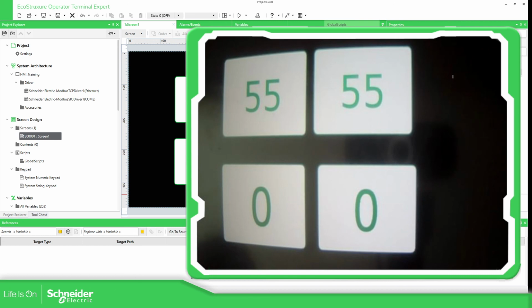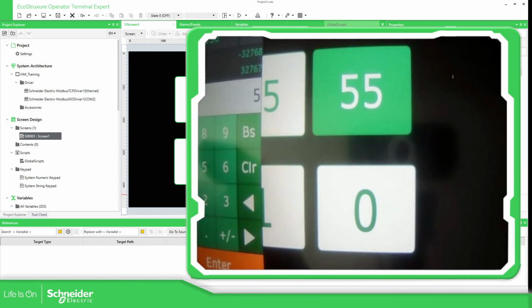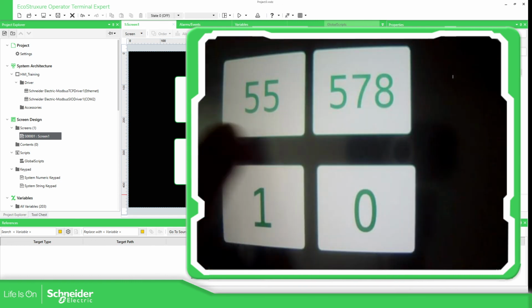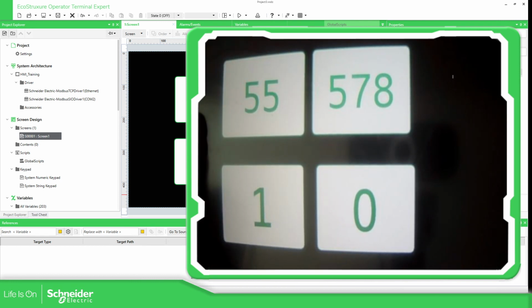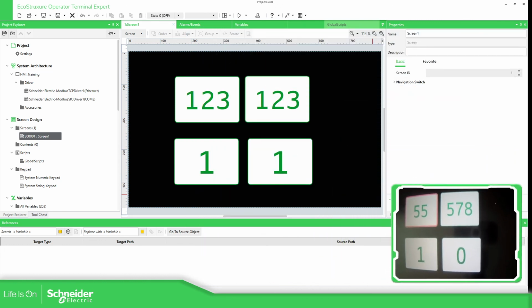Now what I'm going to do is remove the Ethernet port that I have. So it's going to be this side. Okay, so I have removed it. You can see the one that is in fault, and this value is not going to be updated. You can see in there, and in a few seconds you're going to see the square box. Yeah, they're in red. So this is how you can see if you have connection with the device or not.